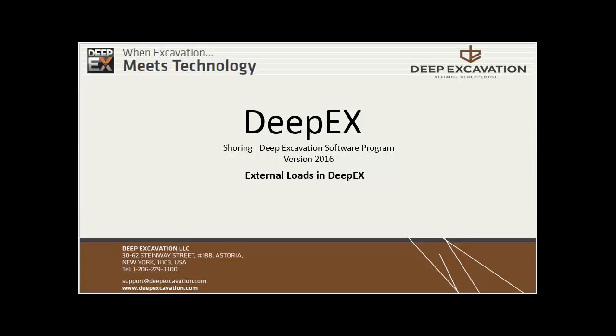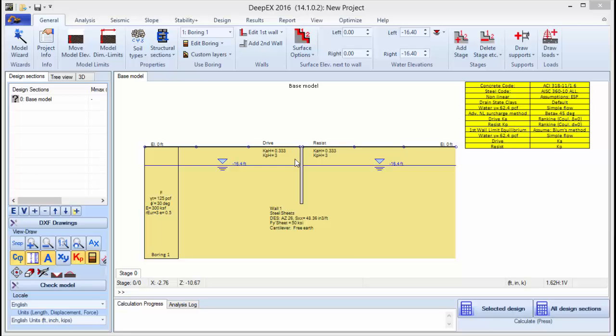External loads in DeepEX software program. In DeepEX we can take into consideration loads that are applied directly on the wall or the horizontal component of vertical loads that are applied nearby the wall on the ground, like traffic loads, construction loads, or loads that come from buildings or footings nearby the wall.